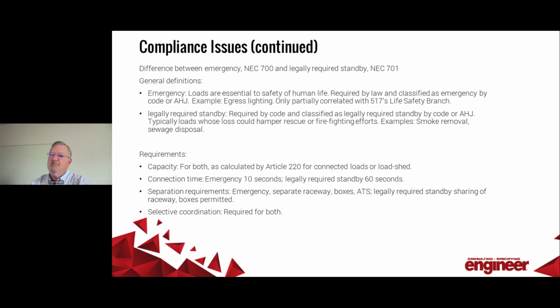A classic example of an emergency load is egress lighting. 701 loads are also required by code or an AHJ, and they are designated specifically as legally required standby. In general, the loss of 701 loads could create hazards or hamper rescue efforts. Examples of Article 701 loads are smoke removal systems and sewage disposal systems.